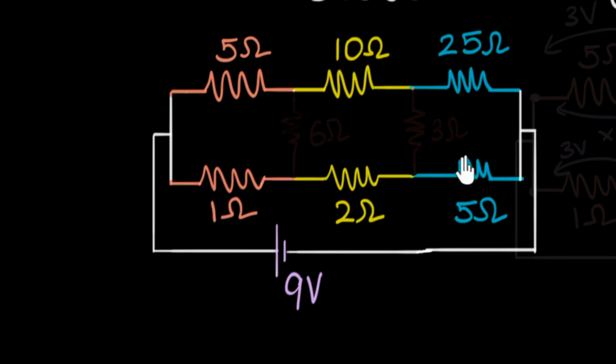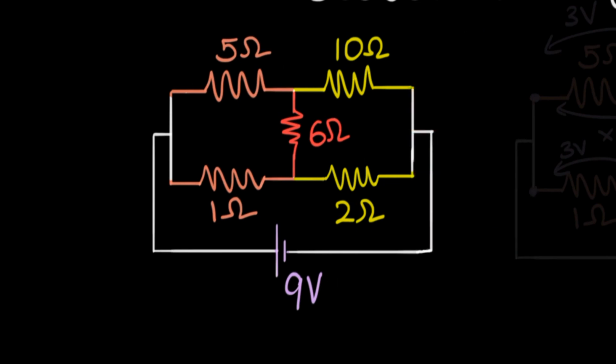All right, let's see. We can apply the same logic. The first step is to first neglect the resistances and then see how the voltage gets divided. Now notice that the ratios of the resistances here is exactly the same as over here, 1:2:5, 1:2:5, which means the voltages will also get divided similarly, right? 1:2:5, 1:2:5.